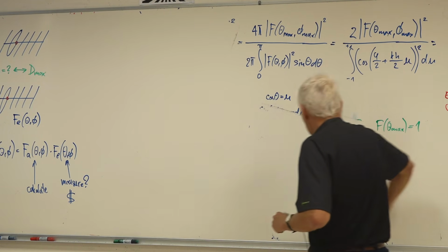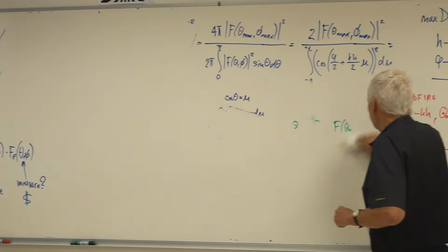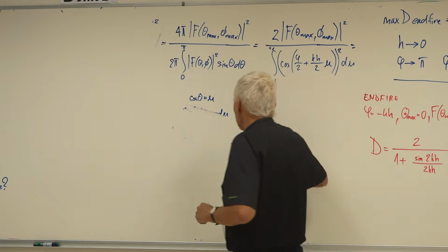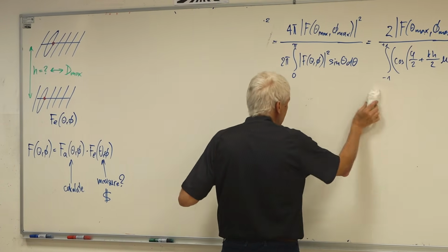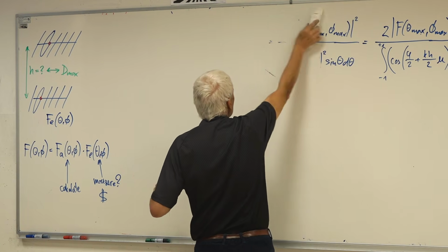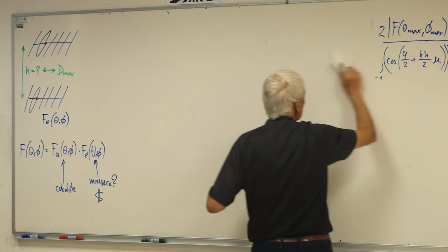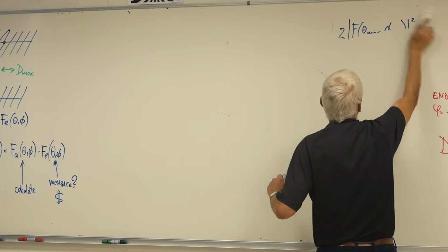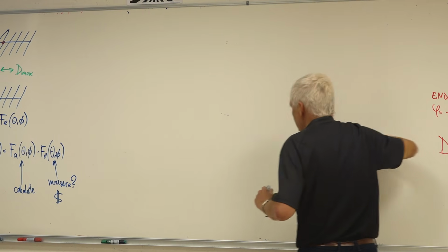You saw that this curve, which I'm just erasing from the board here, was just for omnidirectional antennas, not for antennas that have a radiation pattern. So for a radiation pattern, this derivation is actually wrong. This was just to give you an idea what is going on. Now we have to figure out what is the correct spacing between the two antennas.